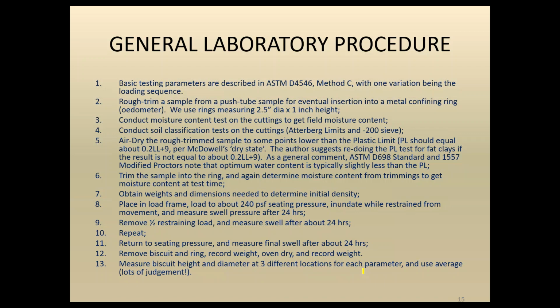And just one thing we do in the lab to reduce the chance that there's an error on the technician's part for that plastic limit value, we found that for fat clays generally, the plastic limit comes in about that value. So we have our guys check, and if they're going to be more than plus or minus 2 or plus or minus 3 out of that value, we ask them to redo that test.